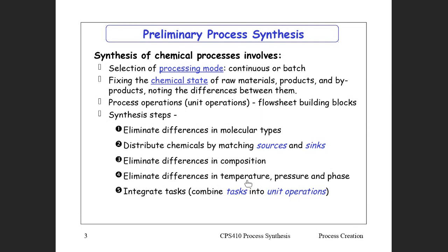So that one's important. Temperature, what you're going to use, heat exchanger, and eventually phase. You might change your phase as well if you need to. A feed material comes in as a liquid, but it must operate in the reactor as a vapor. You would want to boil it off first, because otherwise you can't boil it off in the reaction vessel. Otherwise, the temperature would be wrong.